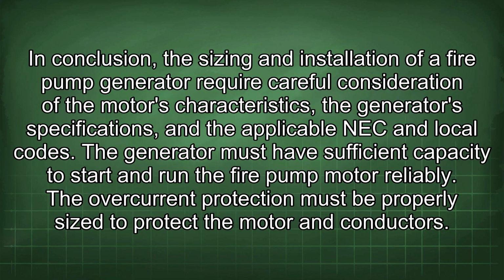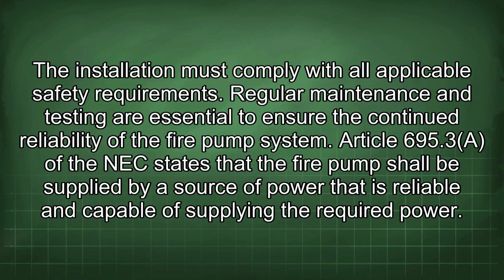In conclusion, the sizing and installation of a fire pump generator require careful consideration of the motor's characteristics, the generator specifications, and the applicable NEC and local codes. The generator must have sufficient capacity to start and run the fire pump motor reliably. The overcurrent protection must be properly sized to protect the motor and conductors. The installation must comply with all applicable safety requirements. Regular maintenance and testing are essential to ensure the continued reliability of the fire pump system.